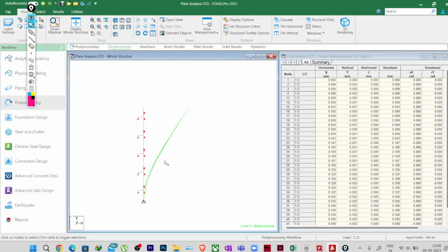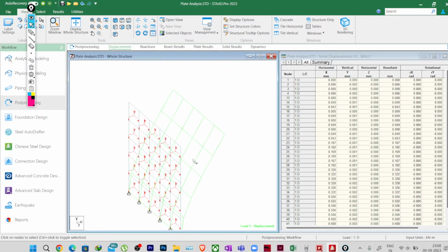Most of the bending is happening along the y direction, and you can see there is some bending happening in this way, like this. So that means in the horizontal direction, this face moment will be 1.404, and this is positive, and this other face moment is a very minimum value, which is negative.